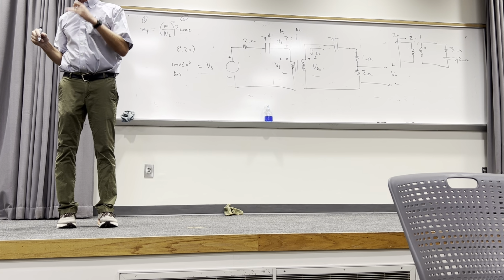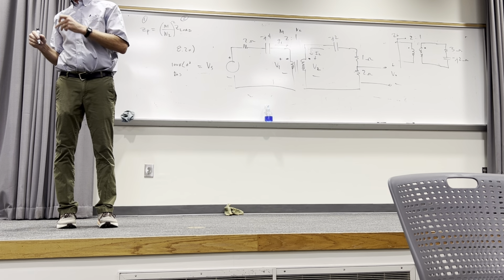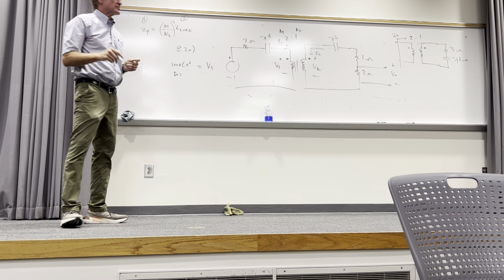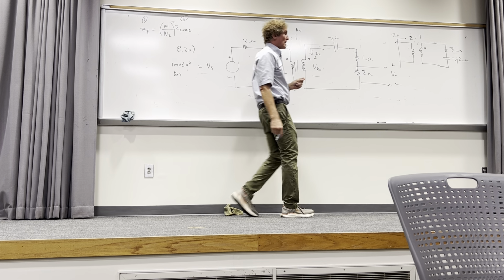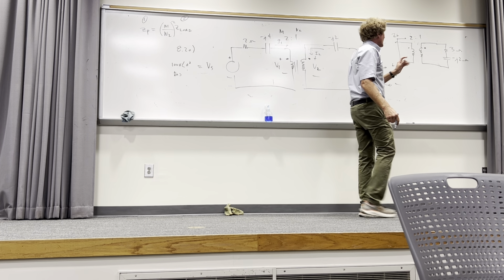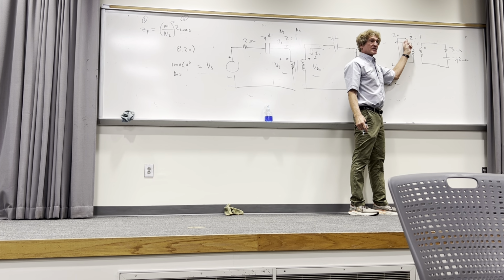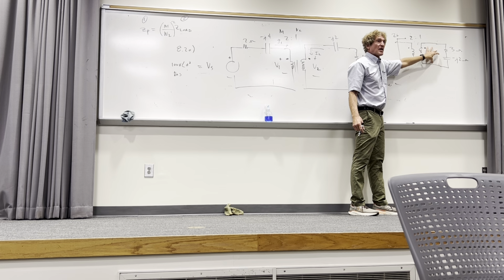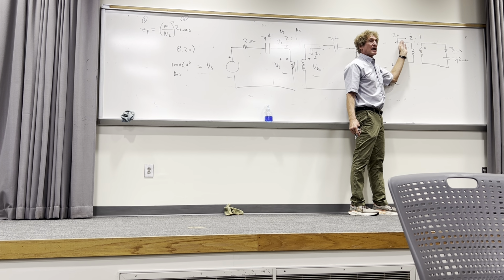Now, I'm going to tell you a guide so you don't make mistakes. Whatever side has more turns, in this case, this side, has more voltage. You all with me on that? So if the voltage here was 5 volts, the voltage here would be 10 volts. You with me? Whatever side has the least turns has the largest current.